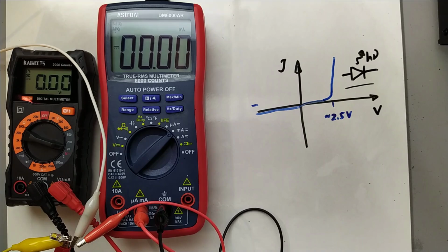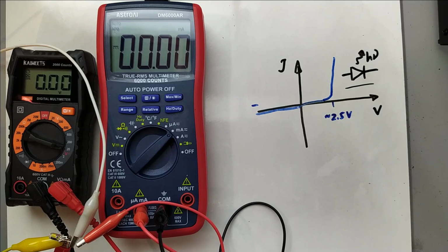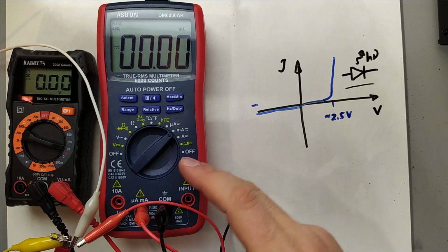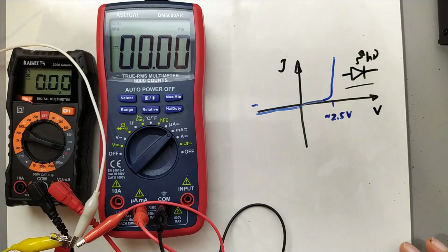So obviously in labs all this power supply, ampere meter and voltmeter are substituted by so-called SMUs, which are source measuring units. One instrument can do this: apply bias, and measure current and voltage drop over your object of investigation as an electrical device automatically and simultaneously.